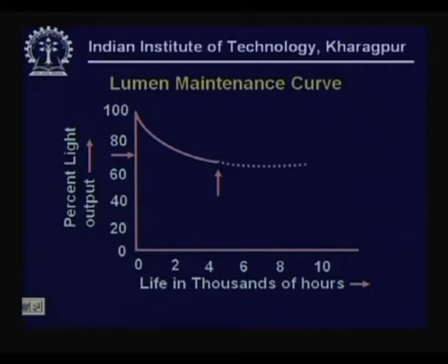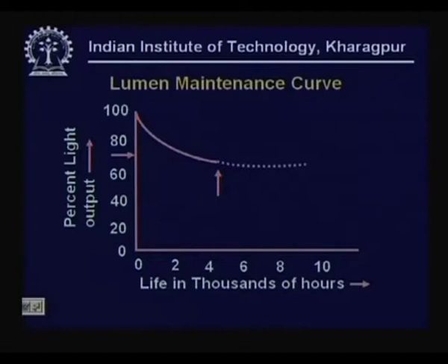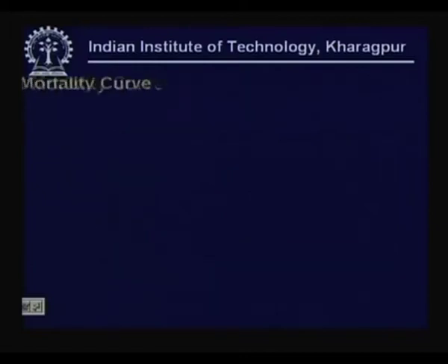This is a very important issue. That means if I take a lamp which has say 1000 lumens in a virgin state, for a very long period, assuming other factors like the phosphor coating remain and the filaments are stable and intact, the lumens or the light flux will be maintained reasonably around 700 lumens. That is what one can interpret out of this curve.